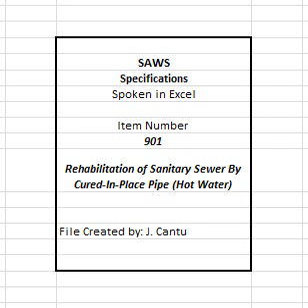2. Manufacturer provided information that describes the CIPP materials, curing speeds, curing installation processes, installation pressures, and temperature limitations. 3. Certified test results of physical properties testing and chemical resistance testing of the proposed resin material. 4. Complete design calculations for the liner thickness per ASTM F1216, for each manhole-to-manhole segment of main to be rehabilitated.